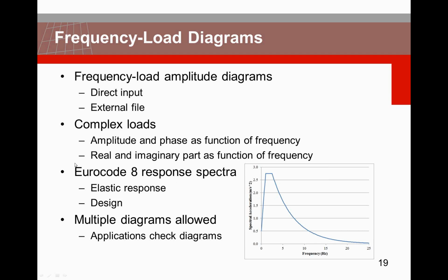For seismic analysis, according to Eurocode 8, you can also let DIANA generate the elastic response spectrum and the design spectrum based on the soil properties and the region as specified in Eurocode 8. Also here multiple diagrams are allowed, and the application will check all the diagrams related to the loading, how much of that load will be applied at that frequency.